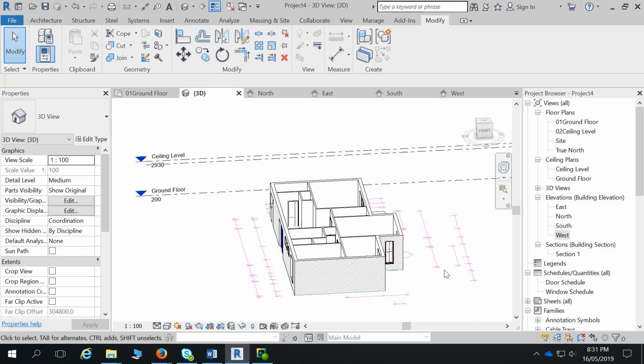So that's your first click, and then you can go to your window. Zoom in a little bit. You can get the top. And see how you get the padlock here. Lock it. So it's constraining it to that level. Why is the padlock over there? It just puts it wherever. So if you click this one, it'll probably be in the same spot. Do I still need to click that line? No, because you've clicked multiple alignment, it doesn't exit out of that. So yeah, the padlock hasn't moved. Okay. So it's just a case of going along and doing everything.